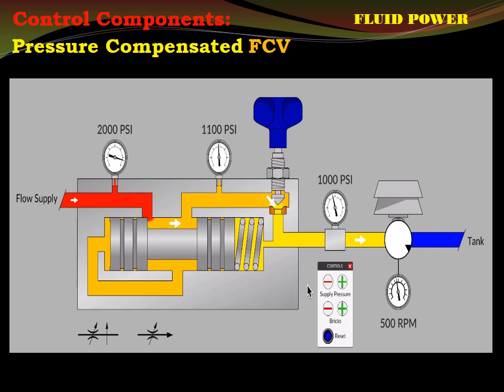Okay, so here is the pressure compensated flow control valve to overcome the difficulty caused by non-pressure compensated valves. I mean it works on a kind of feedback mechanism from the outlet pressure. Okay, it keeps flow through the orifice nearly constant. A schematic diagram of the pressure compensated flow control valve is shown here.